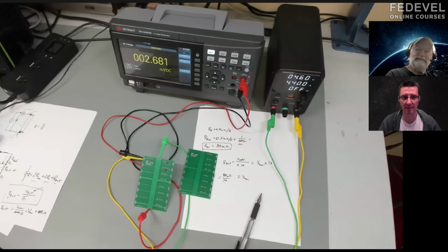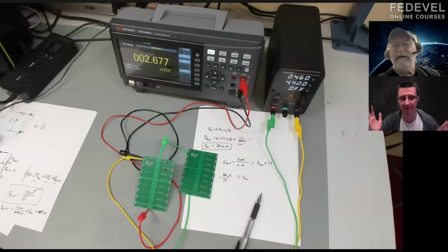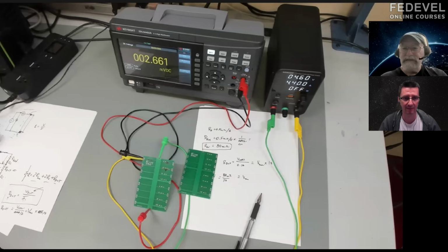So this is what people may see when they are designing, I don't know, some power supplies or something. Sometimes, if they do some special measurements, in the datasheet they say use Kelvin connection. That's what this means. So when we measure, we use a sense resistor to measure current.